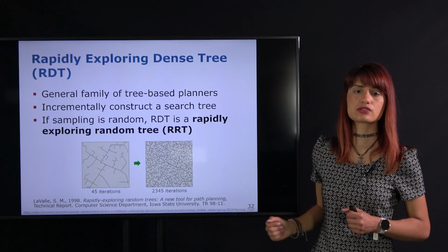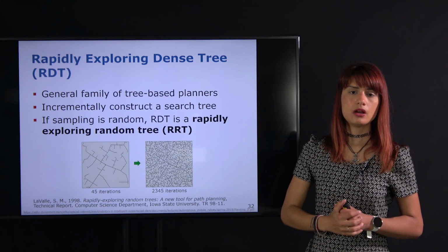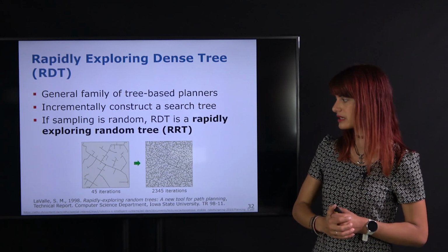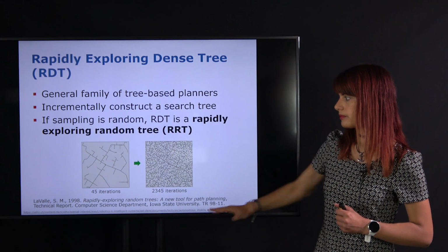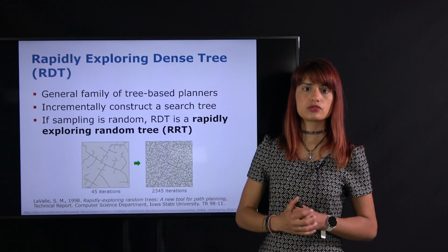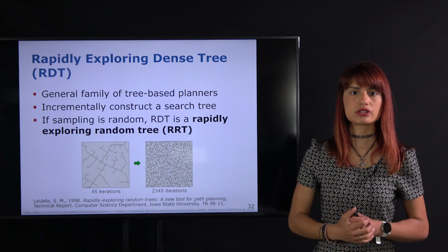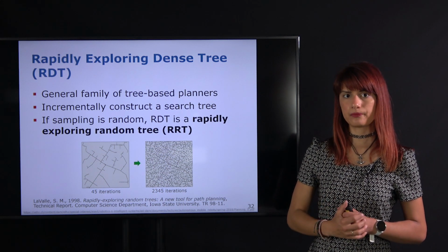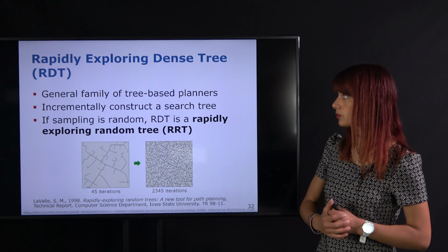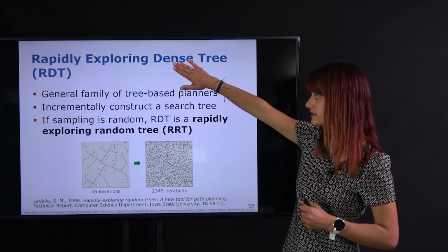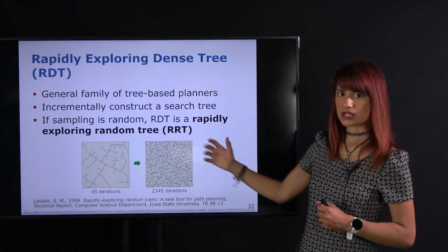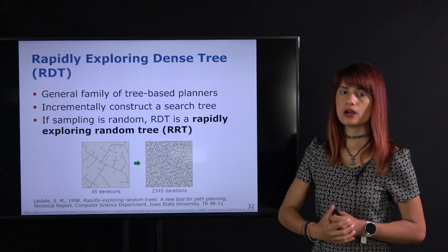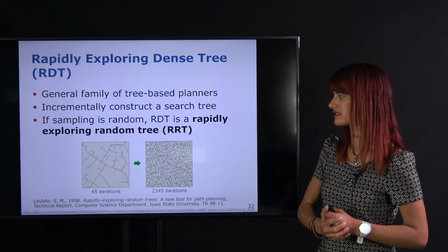And the RRT is an extremely popular algorithm for robotic motion planning in high-dimensional configuration spaces. And its motivation for being introduced was that it's actually able to handle kinodynamic constraints. And we get back to this later. One thing to note is the word dense refers to the branching out of the tree and how the actual tree structure looks over time as we add samples to it.